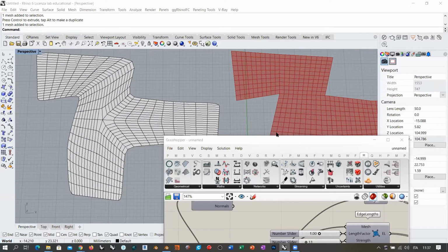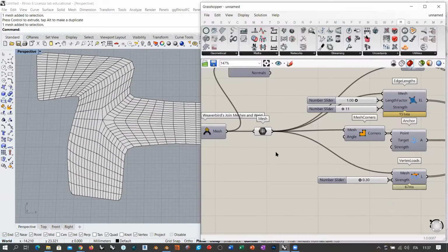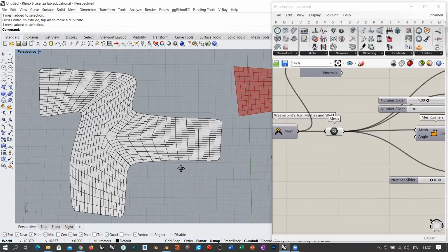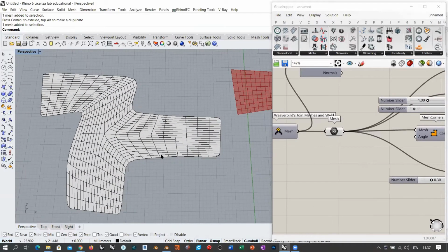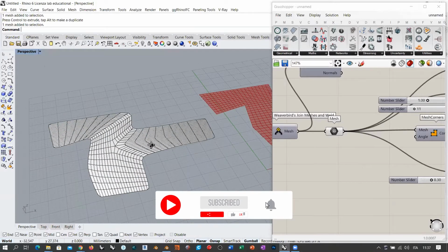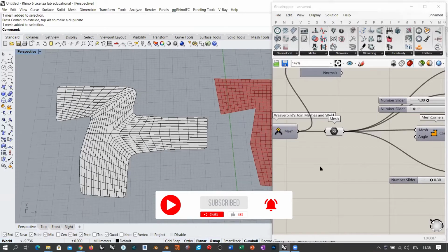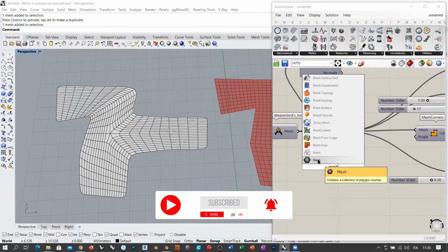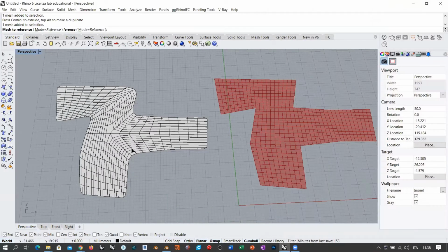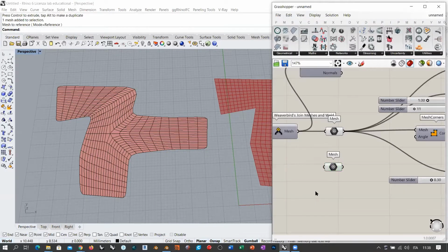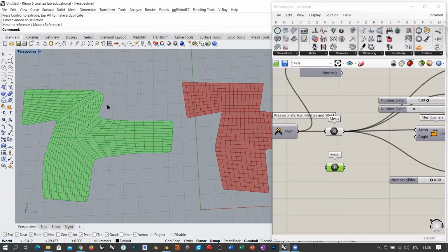But we will be using in a while the Mesh Sync plugin in order to do this operation, because we need to export different things than the ones that we have exported right now. So if I want Kangaroo to work with this mesh, I can take another mesh container, set one mesh, which is this one right now, and I'm going to hide the imported mesh.